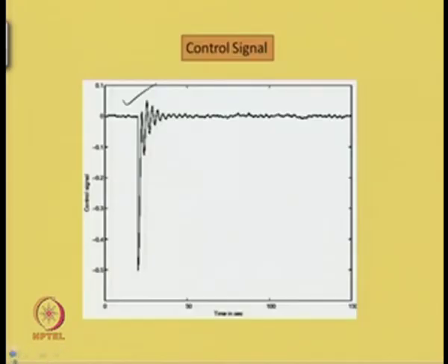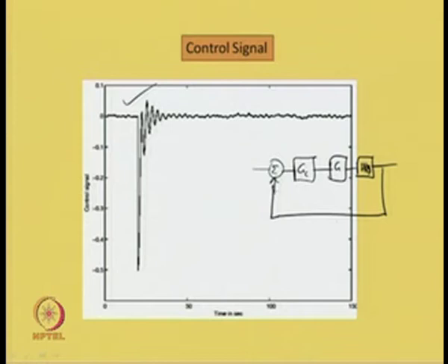So, before going to summary, let us do little bit of analysis over here, why that happens. So, suppose the closed loop system is given like this, we have got a controller GC here and we have got G. Now, this is the measurement noise when we have a sensor over here, as we have been drawing earlier HS. So, definitely there will be measurement noise. Now, without putting a noise filter, what is the transfer function we get for different type of disturbance inputs?